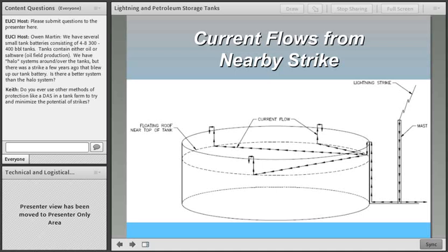And so if there are flammable vapors present, you may have ignition occurring even though you have an overhead shield wire and the lightning terminates on that shield wire. So I hope I've answered your question. From that explanation, you could see why in API 545 there is not a recommendation to install an overhead shield wire.